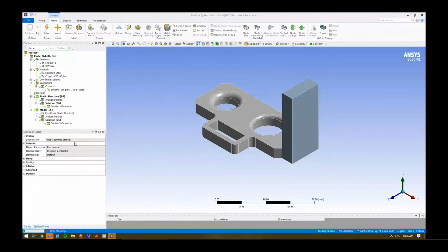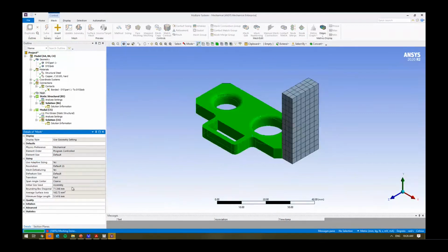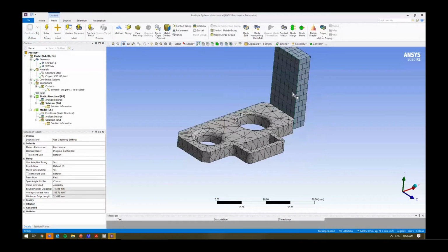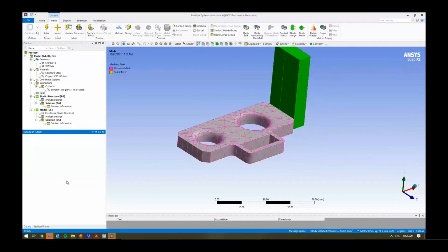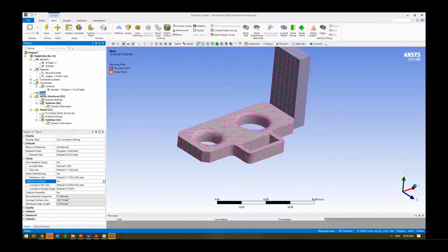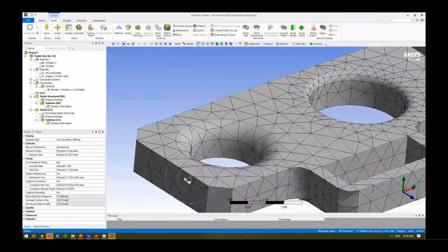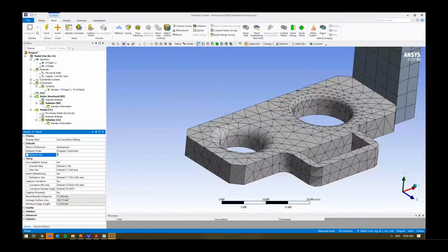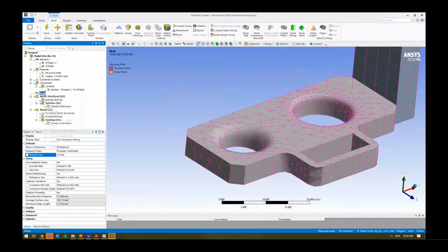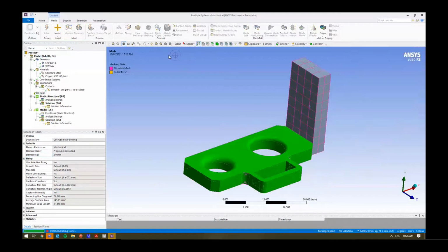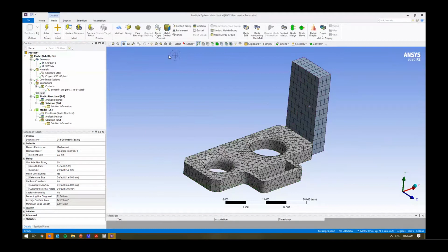Let's just generate the mesh. I'm just going to generate the default mesh that's created, right? So it's a nice mesh over there. It's using adaptive. I'm just going to turn adaptive off. We'll turn curvature on and generate a mesh again. You'll notice it'll capture the curve around here. And instead of 3 mil, let's make the default element size around 2. Right. Again, I just want to run through something quickly.